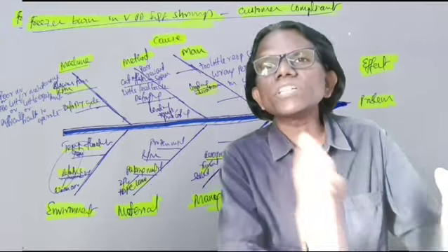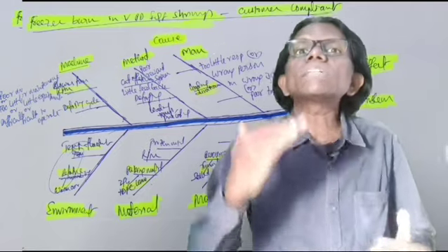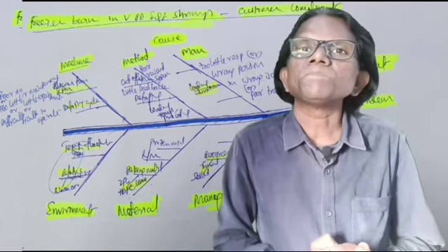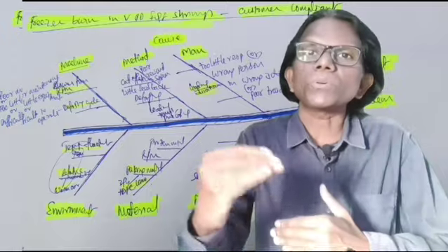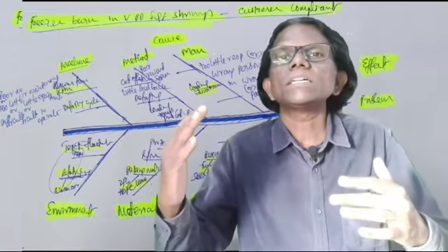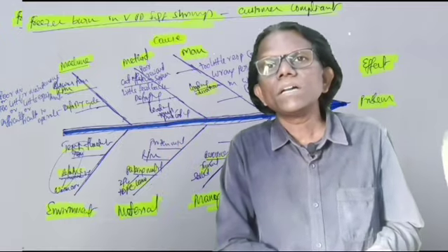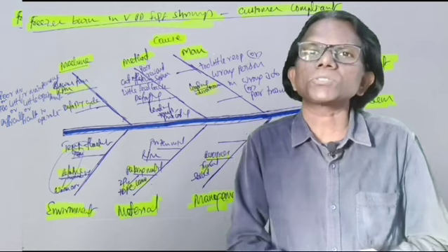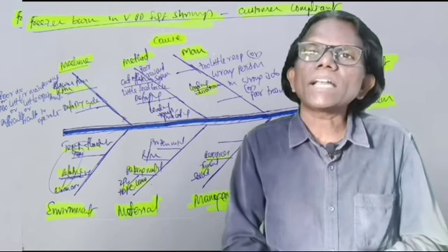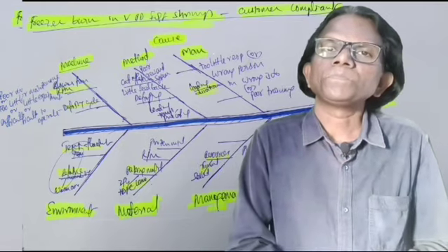Whether we have a hot gas defrosting system or not, and if we have, what is the time of the defrosting mechanism? So these are all things you have to think through. And maintenance of the machineries: whether you are timely maintaining the machines, or poor maintenance of the machines also brings the efficiency and adequacy of the refrigeration system down.